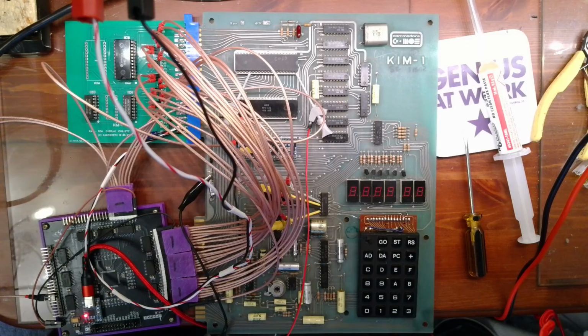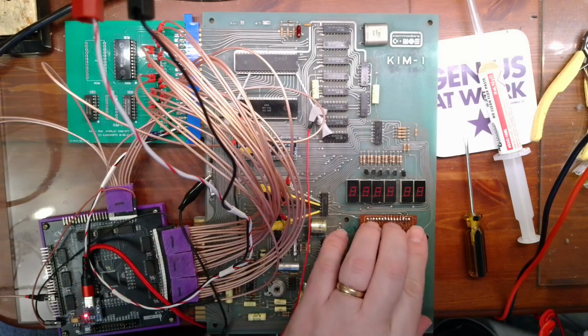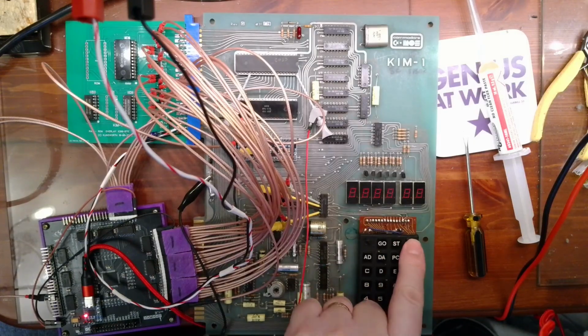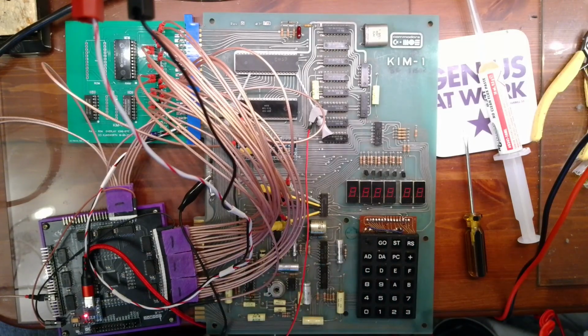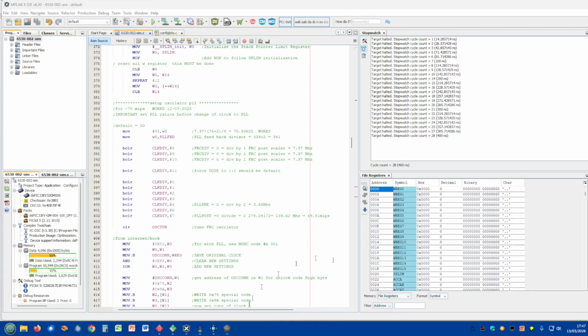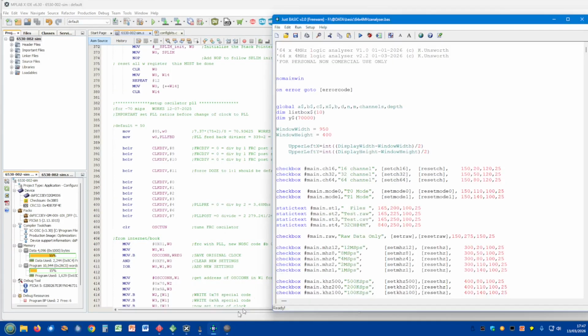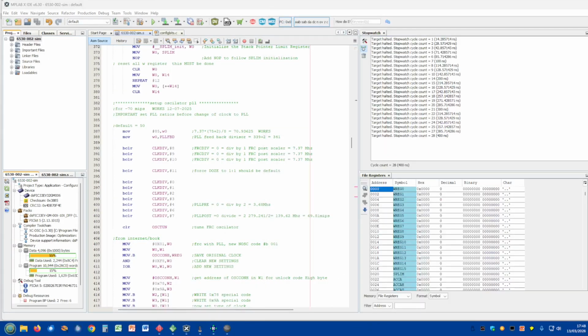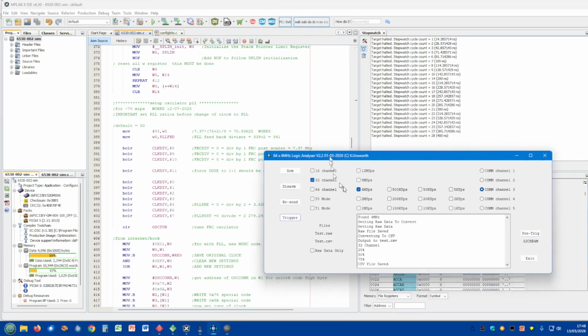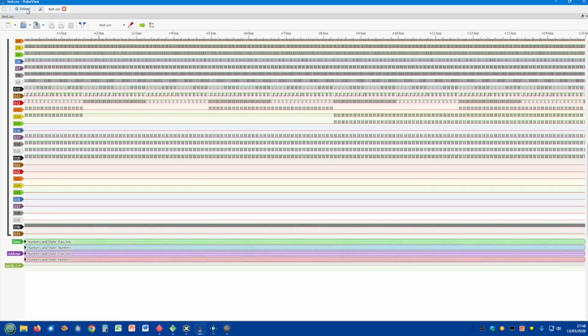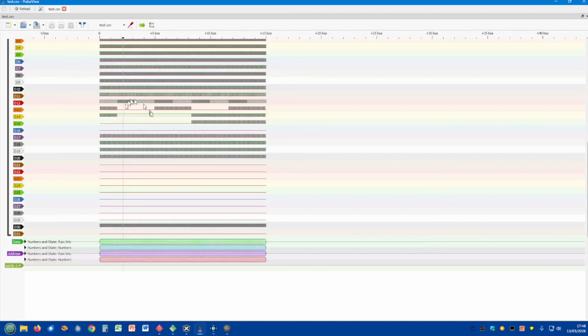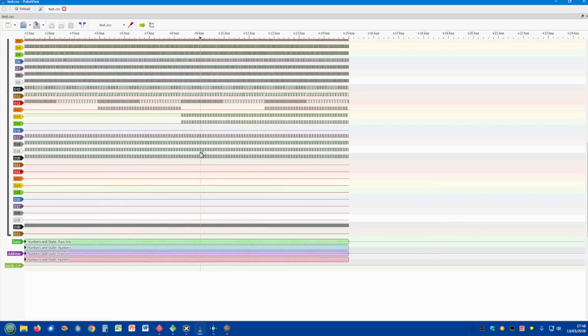Back on the board here, all loaded in, running. Let's reset button. We won't get a display or anything, but we can check what's going on by looking at the analyzer. Whoops, wrong button. Where are we? Oh, we're over there. There's the analyzer box. So if we trigger that now, we can't use the pre-trigger until we've got something we can trigger off. We'll just bring that in, and if we look at that, reload that. There we go. We can see the addresses building up, cycling round as we're just putting data in and out.